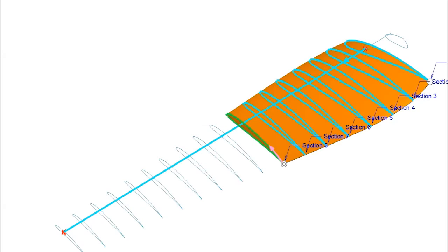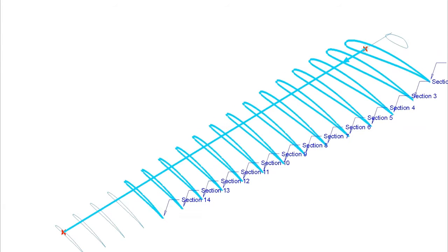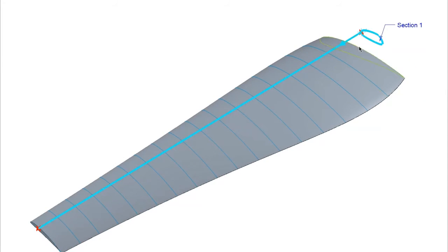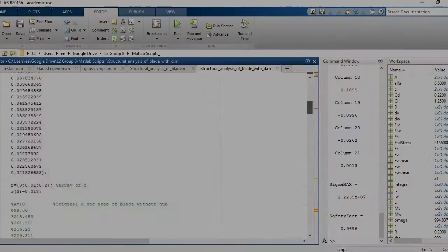The 3-dimensional model required for the printing was produced in Creo Parametric. The aerofoil shape was imported as a spline using a series of data points, and the nose profile was similarly created from a spline, with data points produced using the Haack series equations in MATLAB.